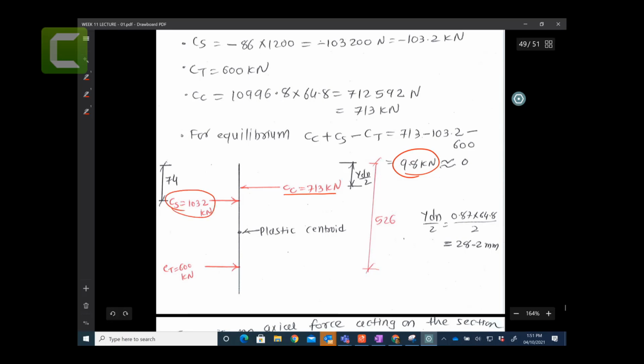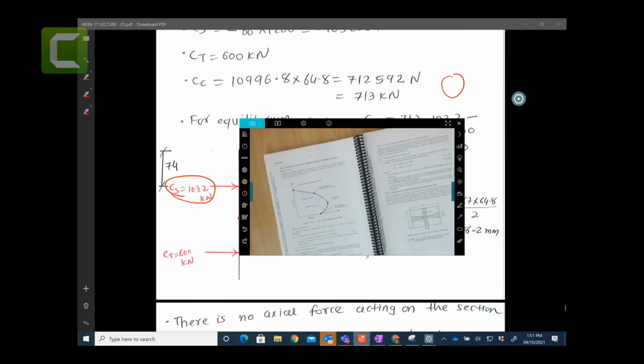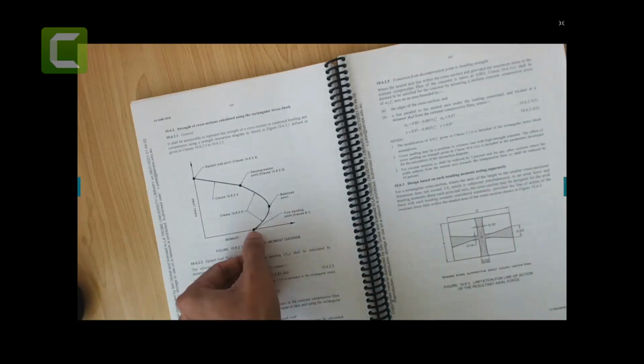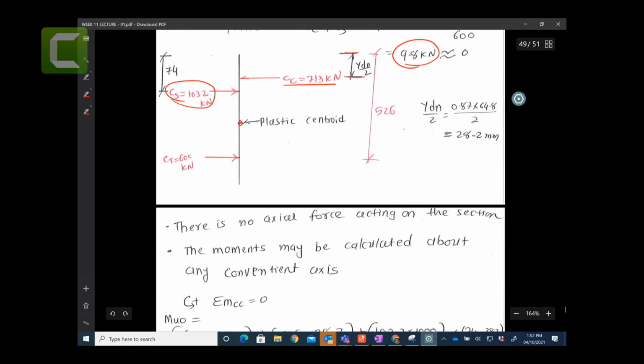By the way, this becomes your tensile steel again, because your neutral axis is just passing that one. So that is compression, all tensions, and follow the same procedures. Same procedures meaning that you have these force times distance about the centroidal axis, and you can find this. By the way, this force is 0, so you don't need to calculate the force, because that's how we find the force is equal to 0 here. For that case, we need to just calculate the moment, right?